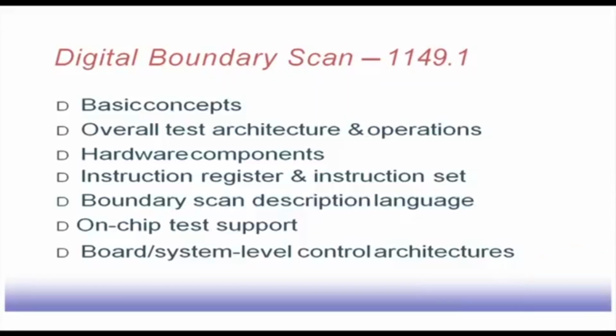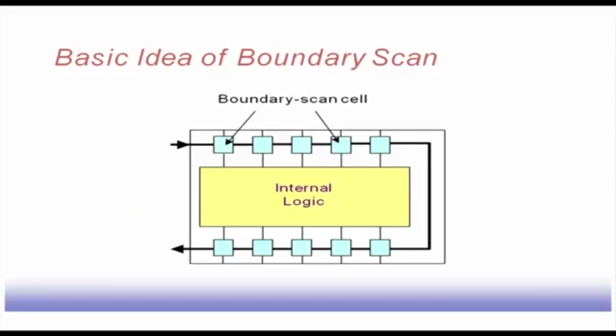To start with, we will look into the basic digital boundary scan standard 1149.1. We will look into the overall test structure, hardware components, instruction register, instruction set, description, scan description language, then the test support and the control architectures.